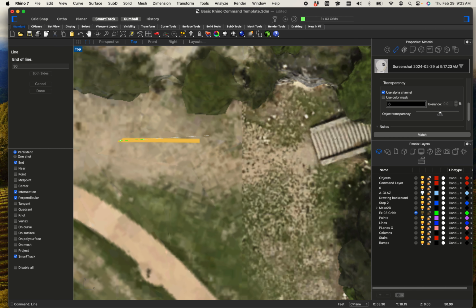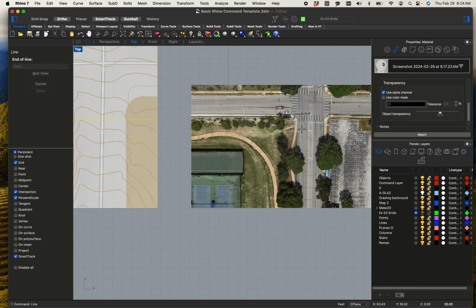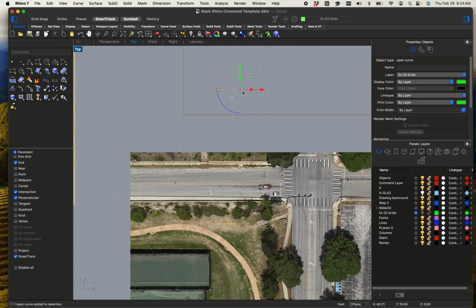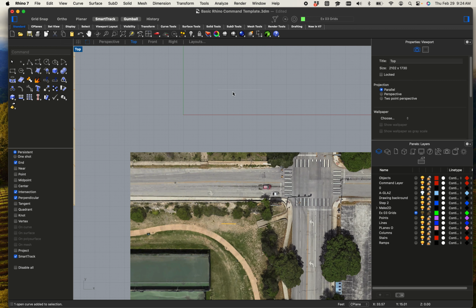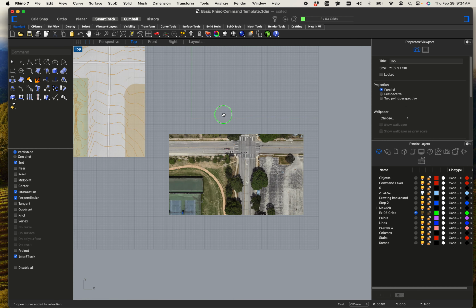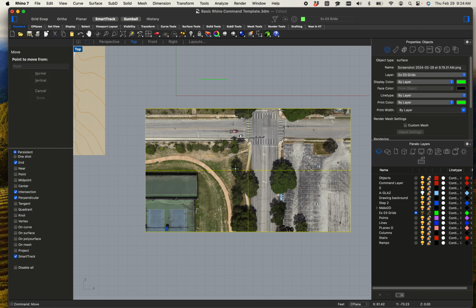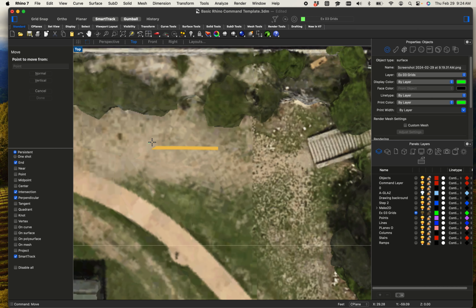I think I decided 10 at first, but then I think 30 feet would have been easier. So there's actually 30 feet according to Rhino, right? That little green line that hopefully you guys can see on the projector. Yep. For some reason it looks black over here. Anyway, first things first, I want to align that. So I'm going to move my image exactly to this line.